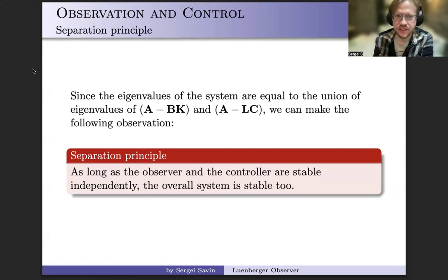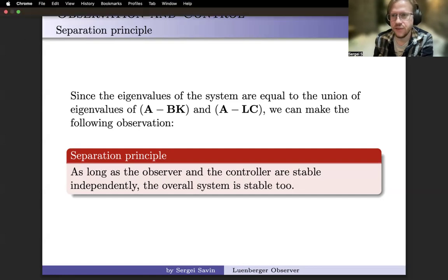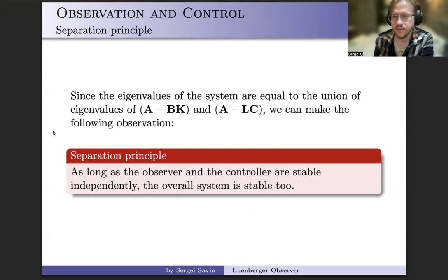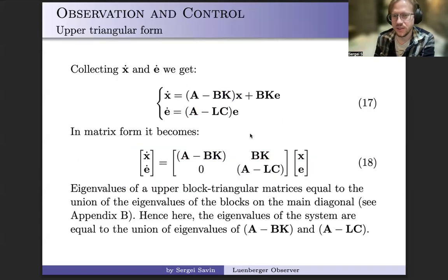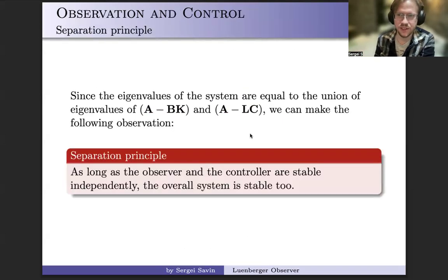What is also interesting is I did all of this for continuous time. And I think if you try to do the same for discrete time, you more or less find the exact same derivation. Right? It's not going to be much more difficult, because notice if you replace x dot with x sub i plus 1, how different are the equations going to be? Not much different. So we don't need to do a lot of extra work for discrete systems. Separation principle and all of that, you can already use it.